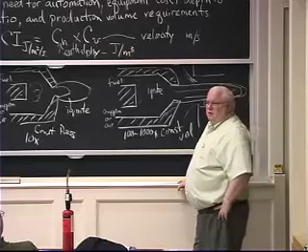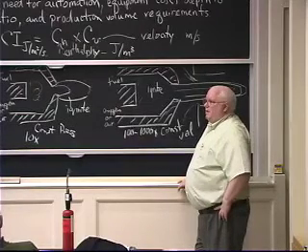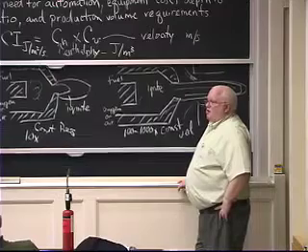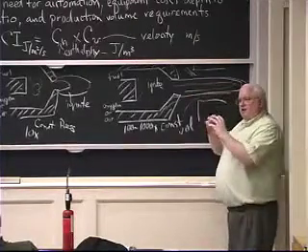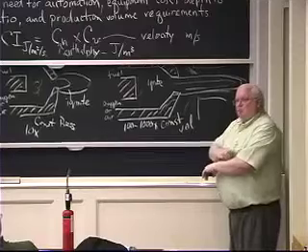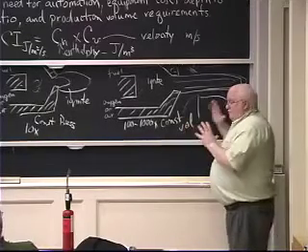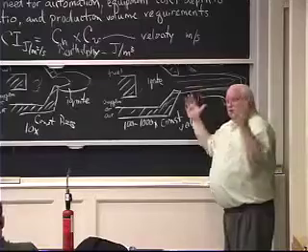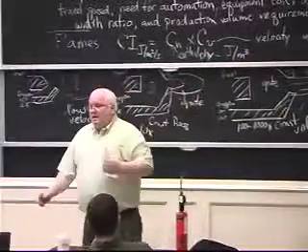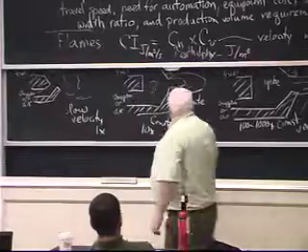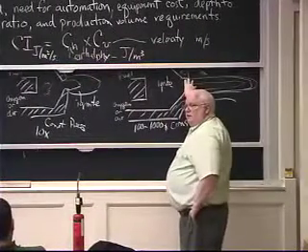So it's a constant volume then too, the afterburner? It's sort of a pseudo constant volume. It's constant volume on 5 sides, but the 6th side is a hole that is shooting out. If you closed off the end of it, you'd have an explosion and the whole thing would go boom once. So it's not really constant volume, but you've got a nozzle that makes it nearly constant volume.